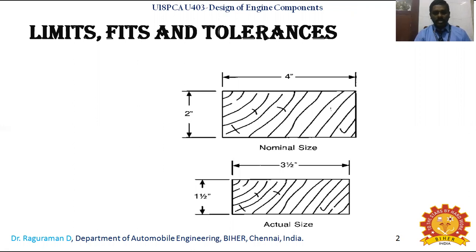For example, if you are taking a connecting rod, it has a middle part called the shank, and the shank has an eye section. The eye section has a separate length and width of a flange. For these dimensions you will follow a design procedure, using Rankine formulas, and you will be checking for the required strength, such as how much bending stress it can withstand.